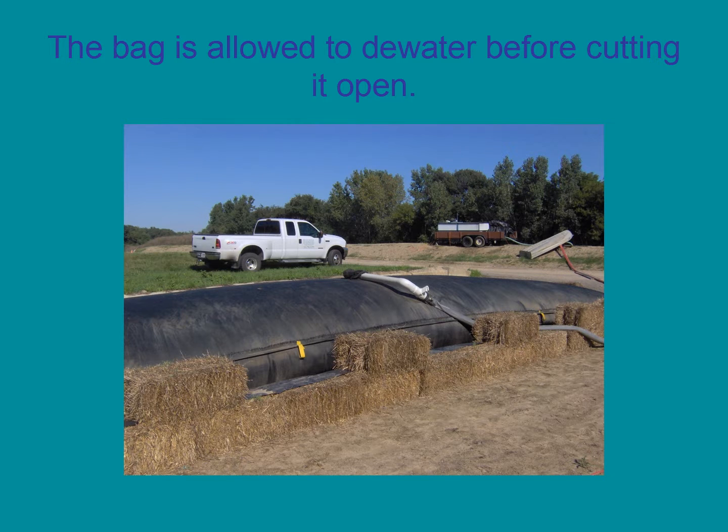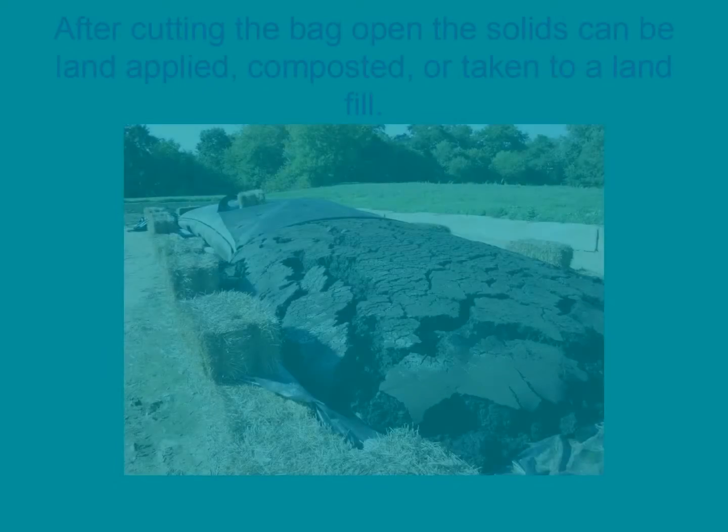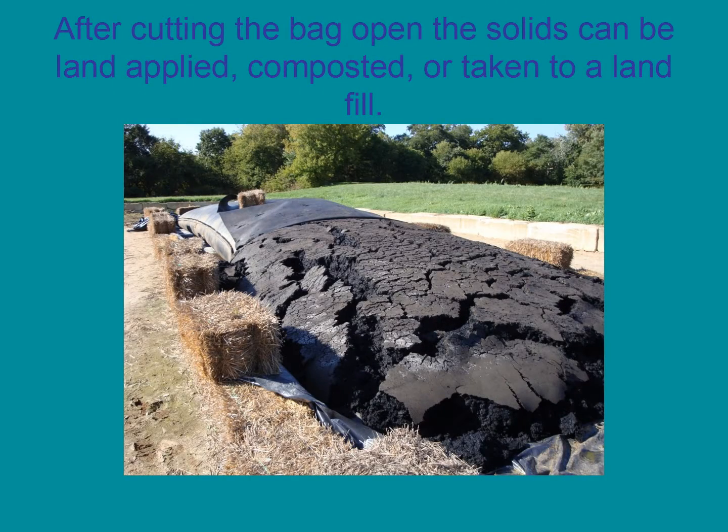The bag is allowed to dewater and dry for a couple of weeks to several months if the plant has the space and the time to wait. After cutting the bag open, the solids can be loaded out, land applied, composted, or removed to a landfill.